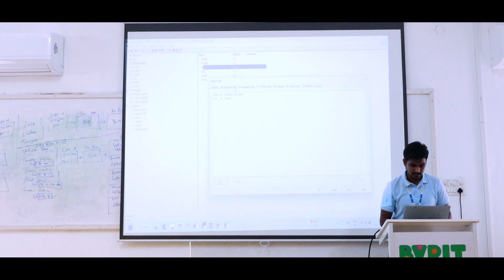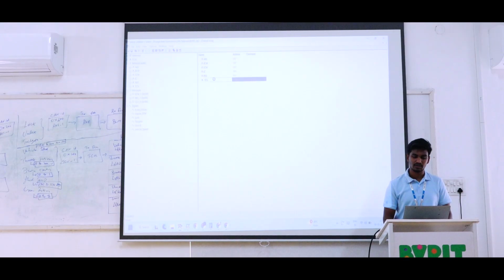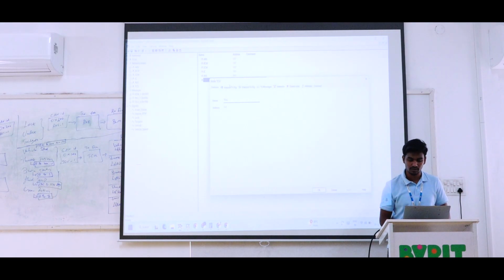So the TX signal is the engine RPM. It is also receiving vehicle speed, which is the previous mapping. So receiving, okay. So now our question is whether we are able to receive it in the TCU also. So going to TCU, map the RX signal, add individual signal, and we can call ECM engine RPM. Right? Okay. So now we can check in our communication matrix.